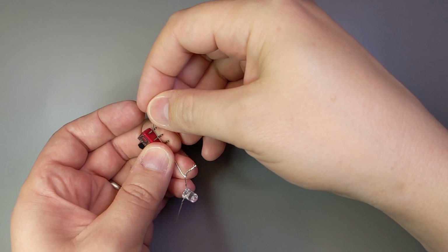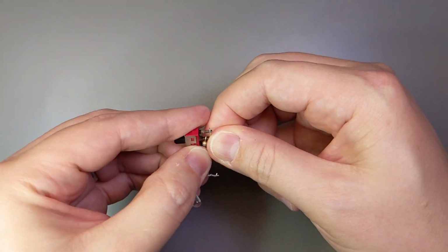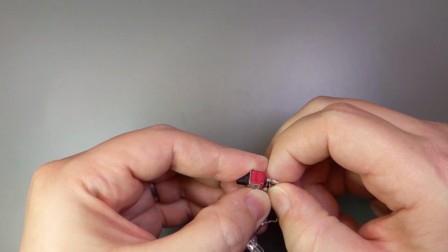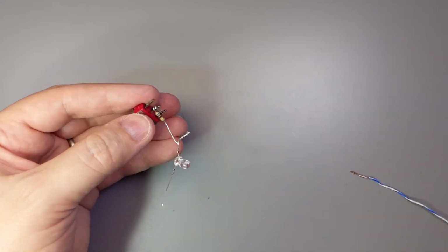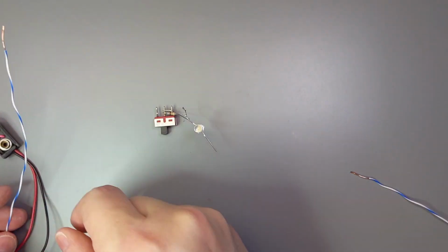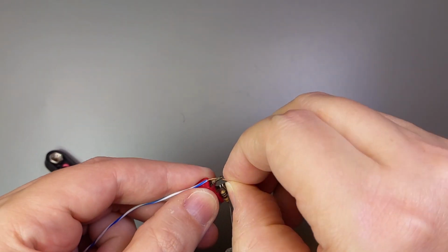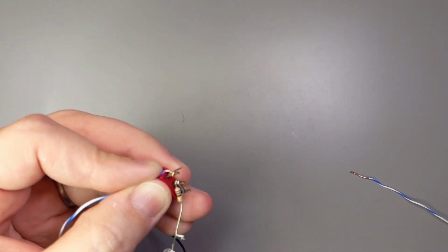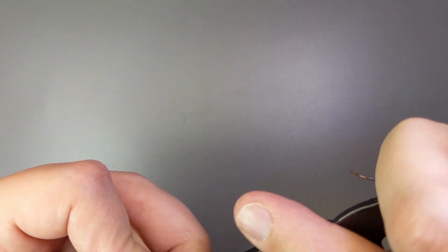I chose to connect the resistor to both of the right-hand terminals on my switch just because this was easier than trying to connect it only to the center conductor. Since we're using the switch just for an on-off in this simple circuit, the third terminal can be shorted out without any problems.